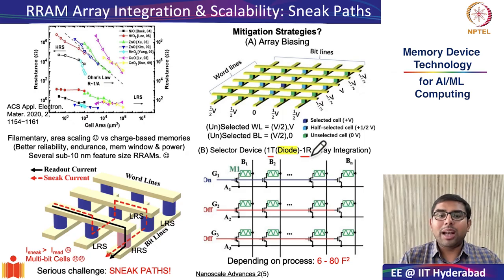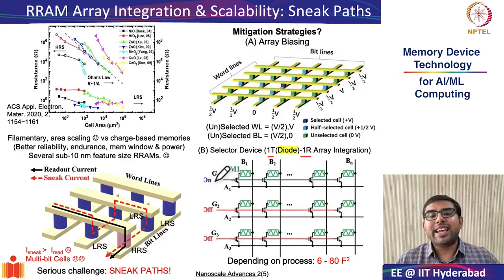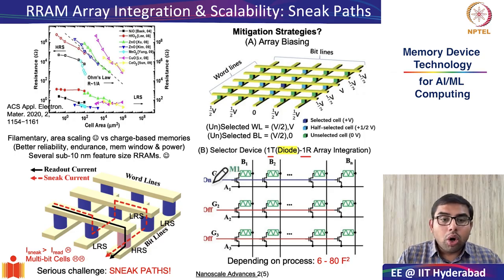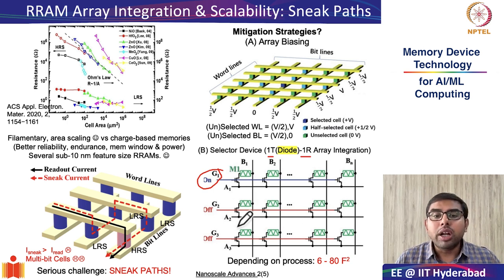So how does this help in reducing the sneak paths? This is done because, just like in a 1T1C DRAM array, only the row which has the word line turned on is active. All other things become inactive. Therefore, the leakage through all other word lines becomes nullified.